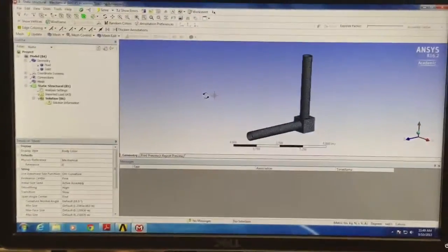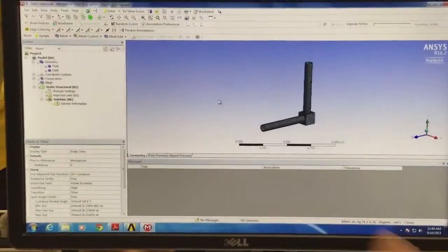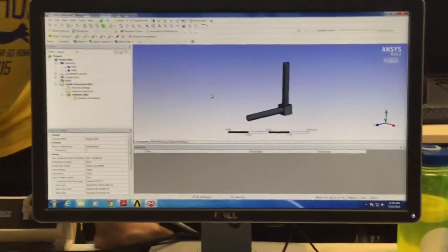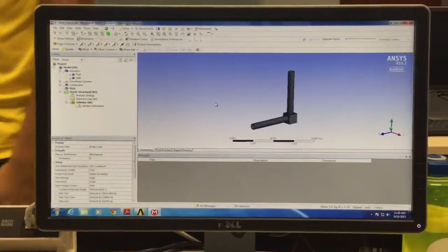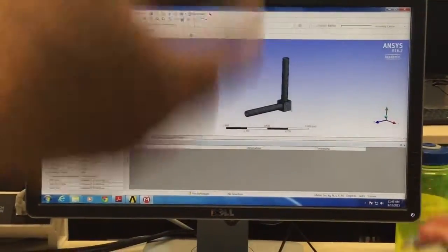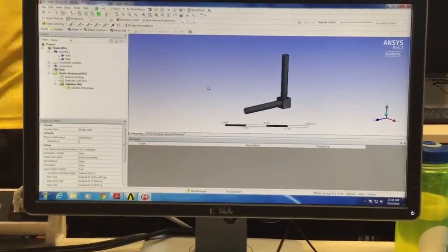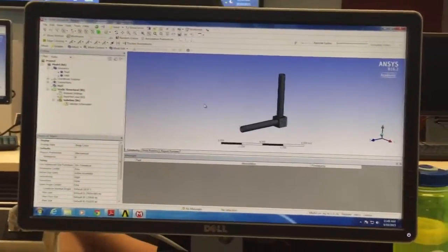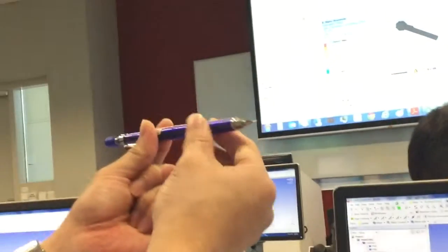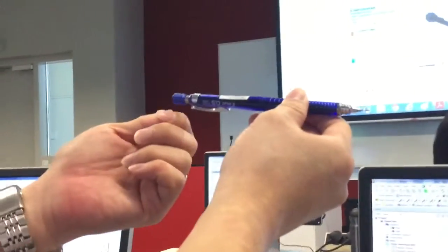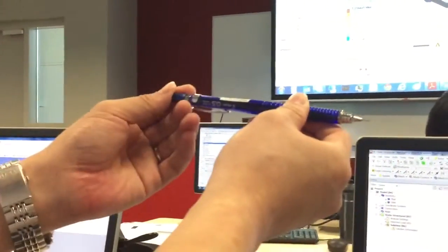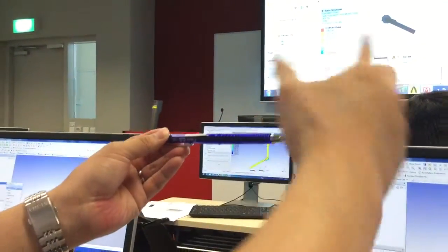Okay, so the next thing is, for structural simulation, what we need firstly is the supports and the loadings of this structure. You need to set a point. For example, cantilever beams. Definitely you have a fixed support here. So what you need to model is just the beam only. You don't need to model this wall. You can just tell the solver this surface is the fixed support. If for example your loading is on this point, then you can select this point as the loading criteria.